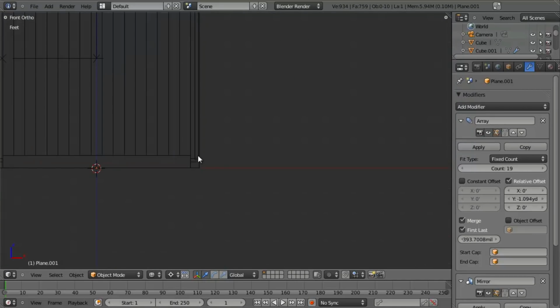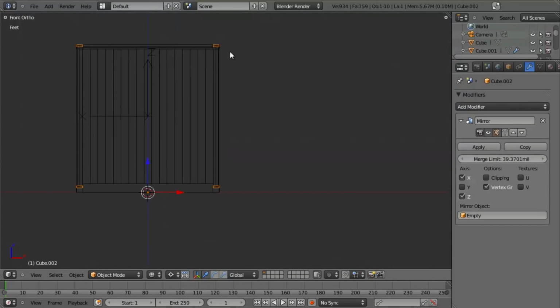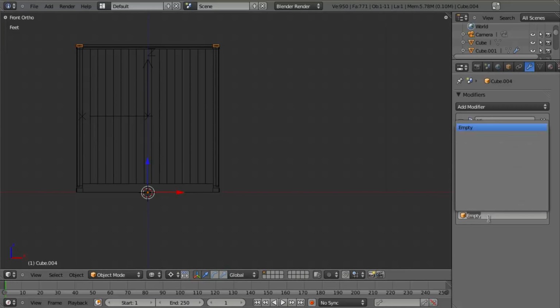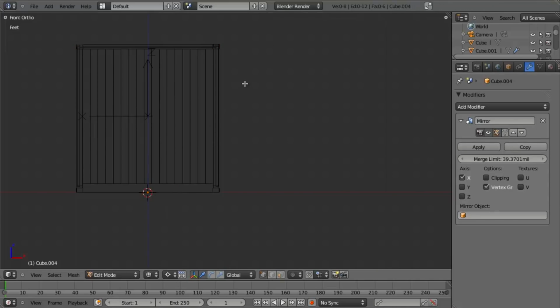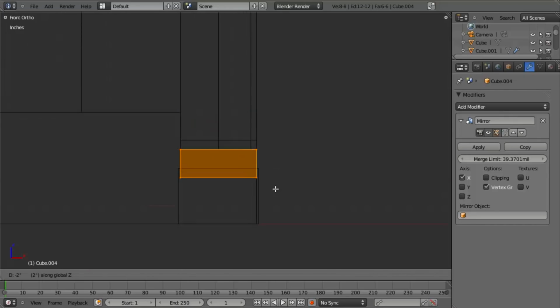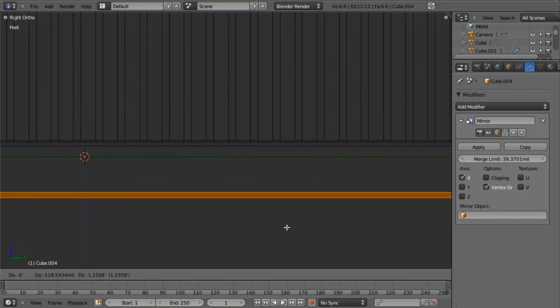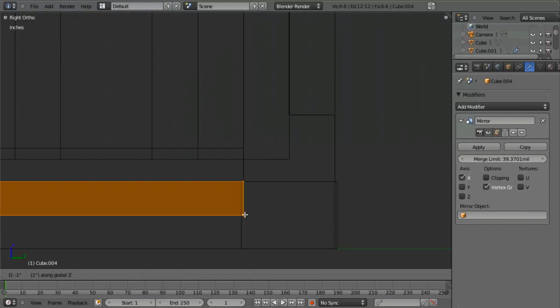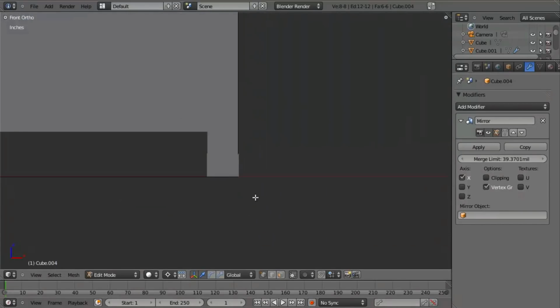So the bottom panel, what I'm going to do is duplicate the side walls. So I'll hit Shift D, right click. Let's disable the Z mirror on this. We can leave it mirrored around the empty if we want, but let's remove this just to be safe. And we'll hit Tab to go into edit mode, select everything, G and Z, pull it down here, and then let's pull it down to be right. Let's see, here we go. Pull it down to right there.